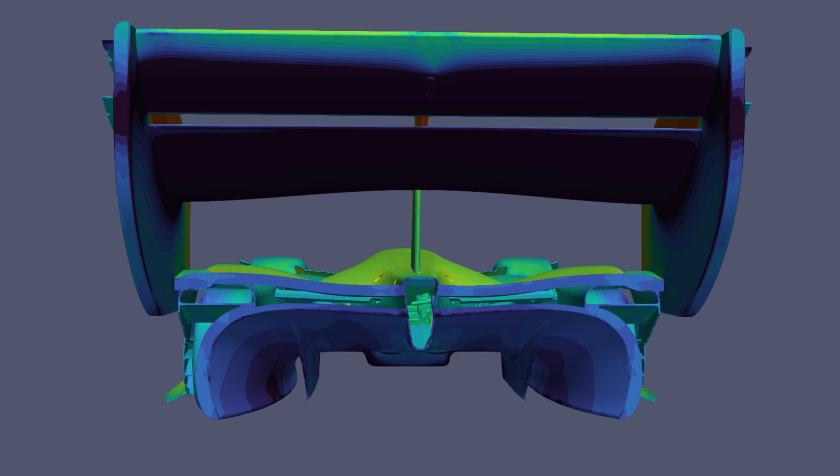There are a lot of times that the underfloor changes don't make sense, and so I spend a lot of time trying different variations. For example, with this particular diffuser, I should be able to have an additional horizontal expansion. The flow is nicely attached, but I'm not getting additional downforce from that additional horizontal expansion. So you just design it to what is most efficient and where the CFD points you.